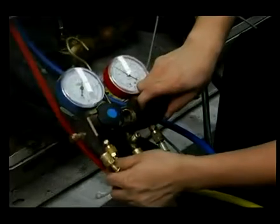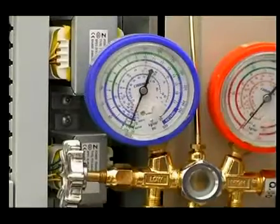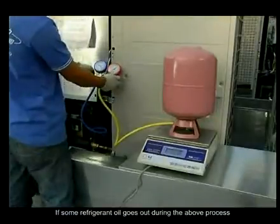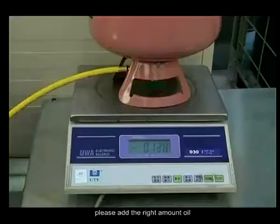If the above problems exist, please discharge all the system refrigerant and vacuum the system. Recharge the refrigerant when the vacuum rate is reached. If some refrigerant oil goes out during the above process, please add the right amount of oil.